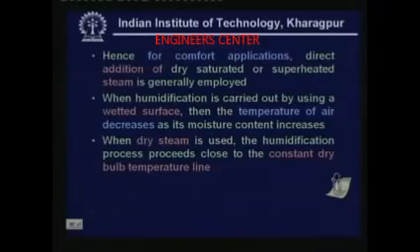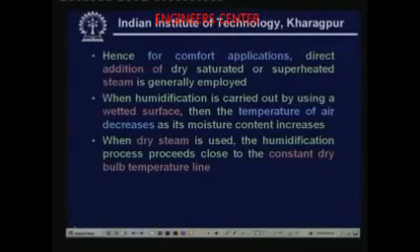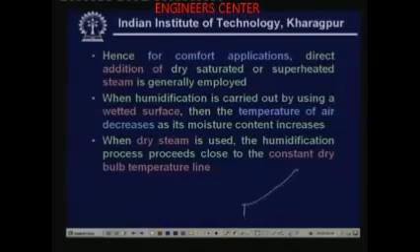However, if you are using a dry steam, then you find that the humidification process proceeds close to the constant dry bulb temperature line. Okay. So I can explain this using a psychrometric chart. For example, let us say that this is a psychrometric chart.